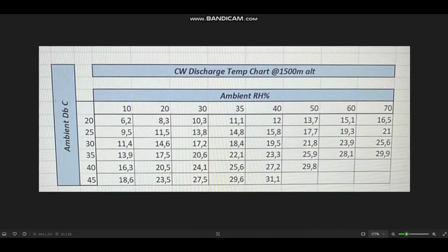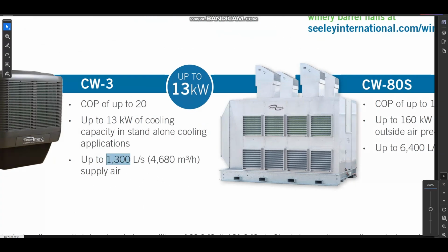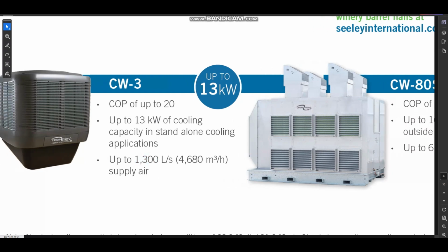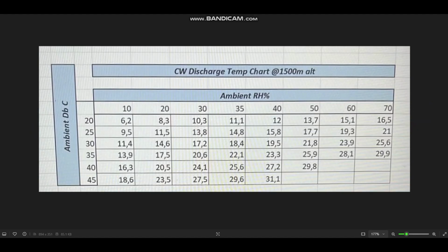This is also done at a slightly lower airflow. So here, instead of 3,000 liters per second, this will deliver the air at 1,300 liters per second. So it's much colder air. It's a quarter of the humidity, probably between 40 and 45%, and the air is moving much slower. This is the long and the short of the question. What temperatures can I expect in my room? So with Climate Wizard, you'd be looking at a real feel of 21 degrees Celsius given these conditions.